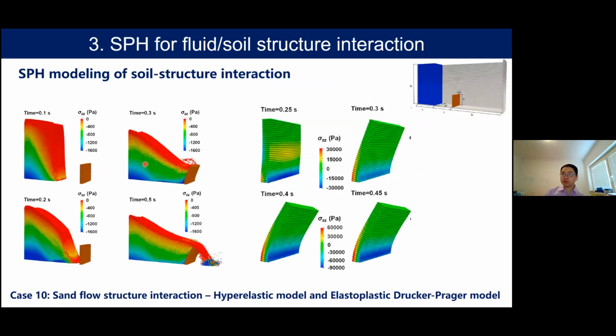If we change the materials into sand, we can also simulate this. And here, the important part is the modeling of the solid part, that is the elastic part. Usually in SPH, it is difficult to get an accurate stress field, but with some improvements, you can still get the accurate stress field, and the simulation of the elastic solid can be achieved.